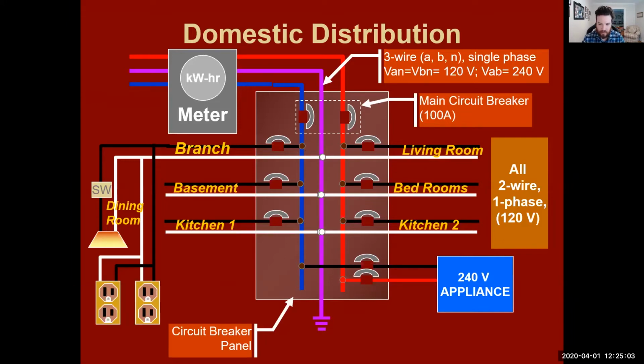All right. So what we're looking at here is instead of having one live wire, we have two live wires coming into our 240 volt. So we have two 120s adding up to 240. Okay. And that's why, if you pop open your circuit breaker panel, you'll see two circuit breakers with a bar across them, connecting both of them. And that is a 240 volt circuit breaker. All right, because it has two live wires coming out and going together in conjunction.